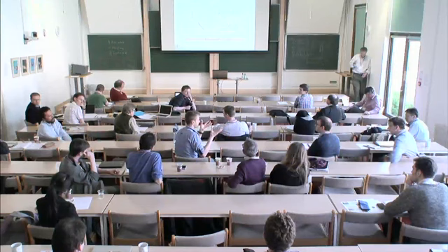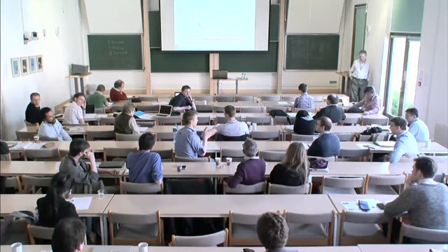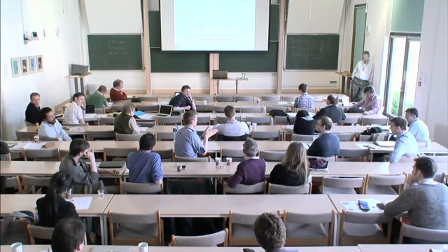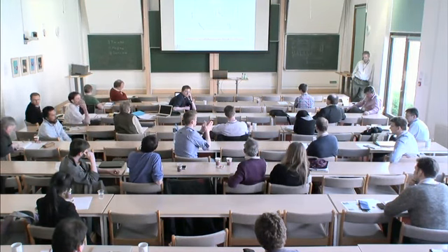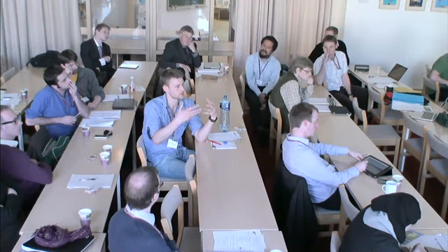I feel like we're looking at using storage for two different things here. One is smoothing out the short peaks, that is a short-term usage, and the other one is actual time shifting of supply. It seems very much that depending on what we use storage for, there would probably be different locations in the grid that would be more appropriate for it or not.